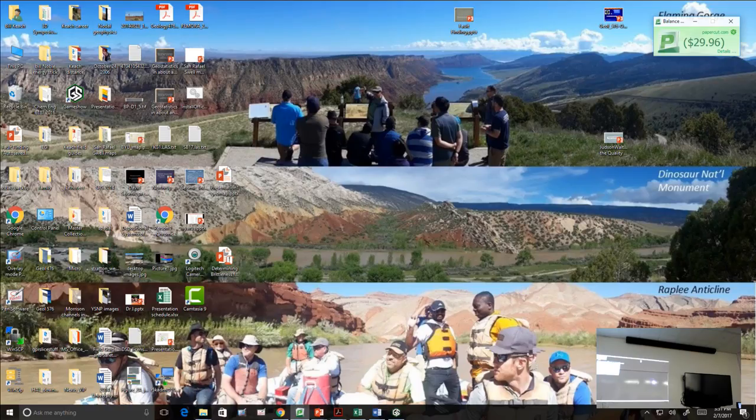Okay. So put your cursor on the top. Just go into arrow mode. Now put your cursor on the face. Hold down the Shift key. Now push down the left mouse button. Hold it down. Okay, yeah, there you go. And you can do that on any face. You could have also brought it up and down by just grabbing the handle on the side of that.